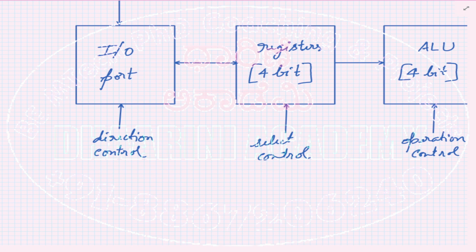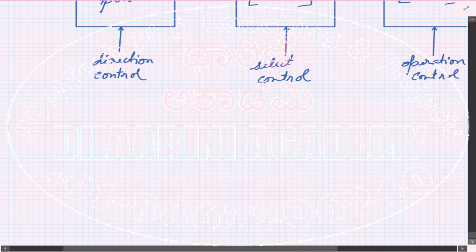Once this is done, the next step is to perform what is called floor planning. This is to perform the relative disposition of the subunits on the chip. So now I know the block diagram, but this has to go onto a chip. So that will be your next step in the design. Then we are going to perform a tentative floor plan.